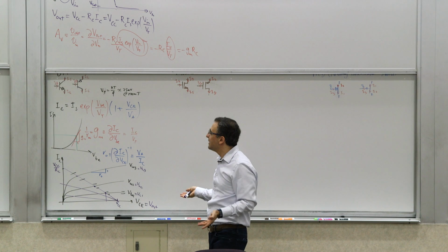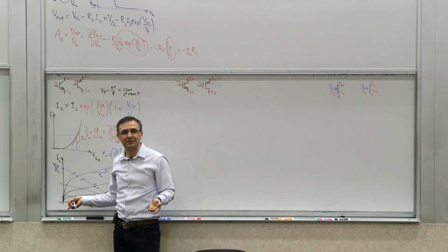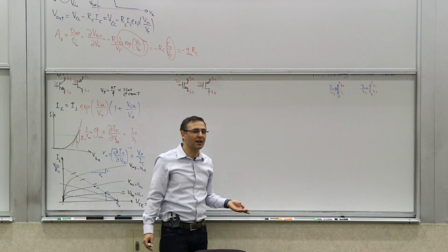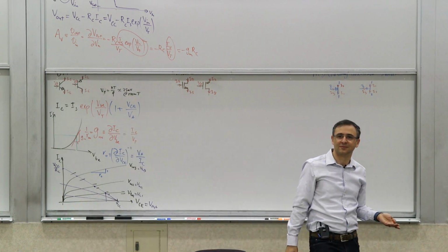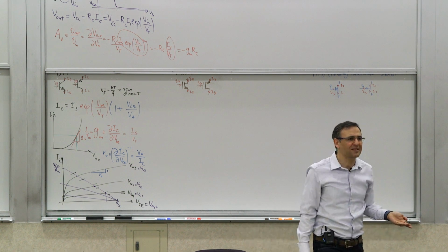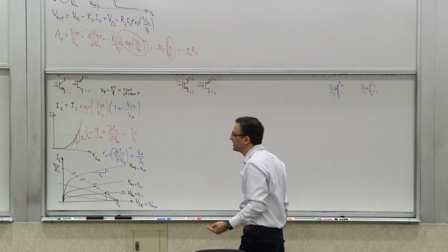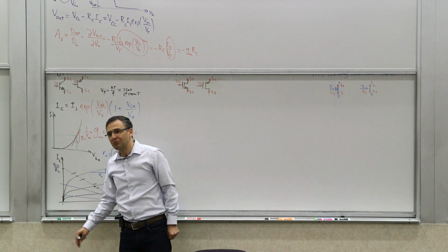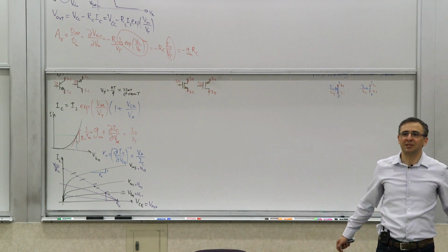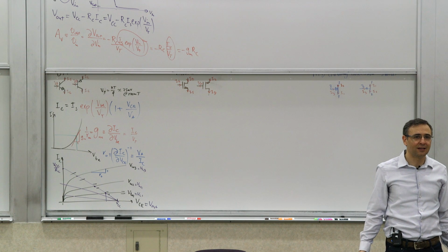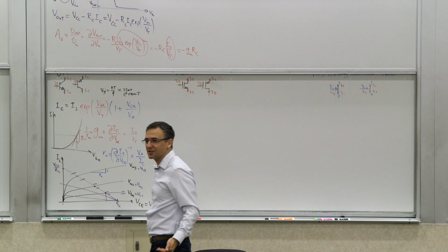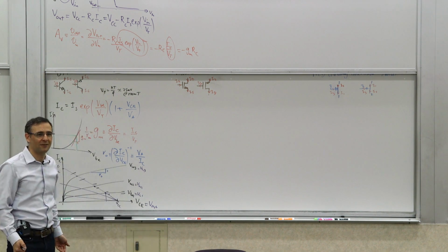If I want to take this to the limit, what would happen? Well, the limit is down here, right? What is my collector current in that case? Zero. So there's no current flowing in the device. Now you may say, well, I want to make it very, very small. It may not be zero, but very small. Yes, you can do that. But a very, very small current, as we'll see later on, would correspond to a very limited ability to drive anything. Especially if you have a capacitor, it would take a really long time to charge and discharge that capacitor when we get to it.